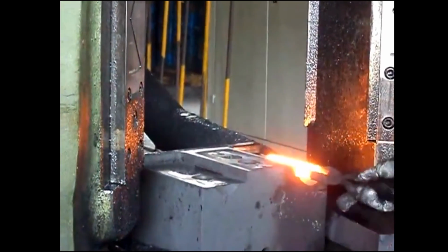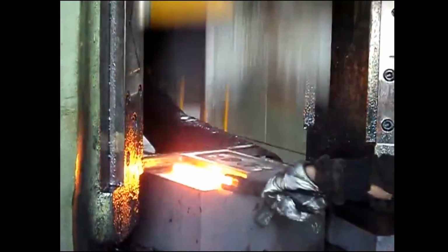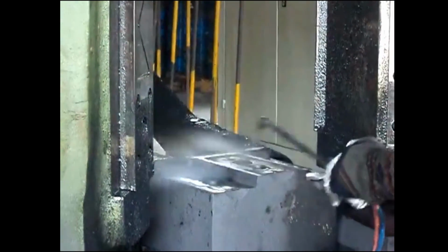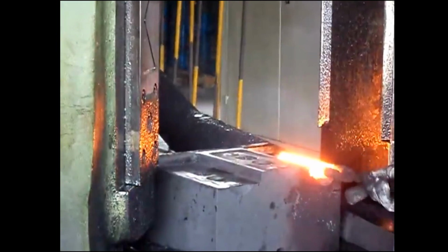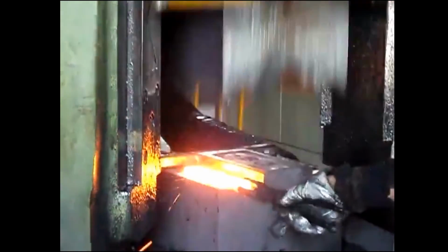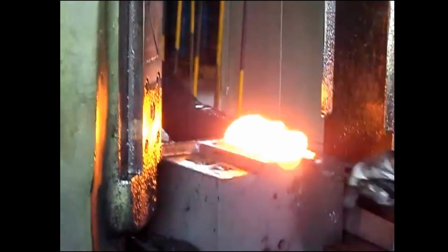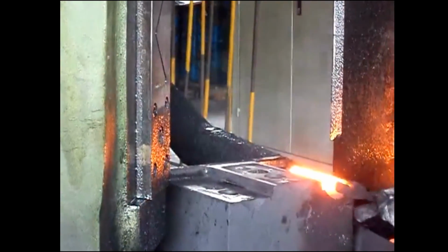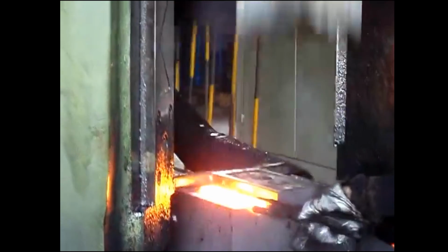For the connecting rod, the best is to give some annealing treatment after the forging process to relieve residual stresses, to increase ductility, as well as to improve machinability and dimensional stability. No surface treatment is required.